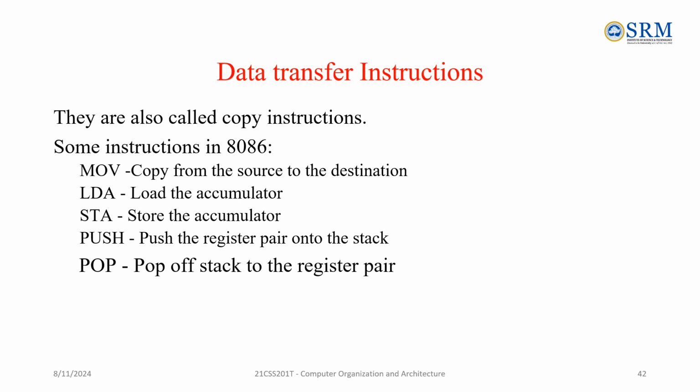So data transfer instructions are also copy instructions where data is moved from one location to another. Some of the instructions are MOV, LDA, STA, PUSH and POP. MOV is copy this from the source to destination. LDA is load the accumulator. Accumulator is a special purpose register. And STA is store the accumulator. PUSH is push the register pair onto stack, and POP is pop out from the stack to the register pair.